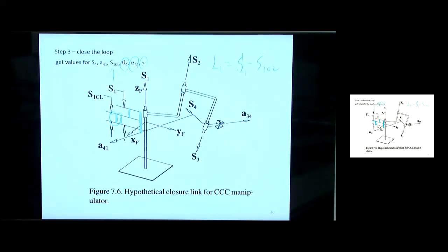So it's kind of similar to what happened where the robot wanted phi1, and that turned out to be the angle theta 1 that came out of the analysis of the closed loop 4-bar minus the gamma that came out of the closed loop. So we got something, again, it's funky. For this to be the first problem, I didn't want to really introduce weird stuff.